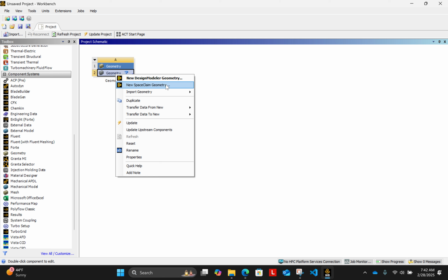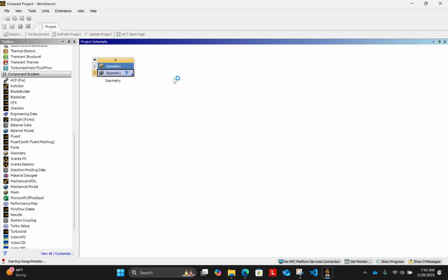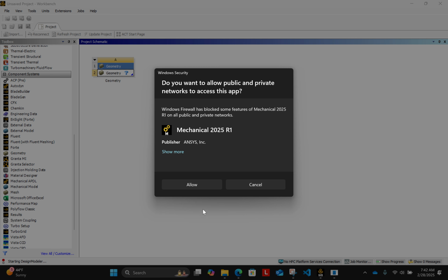They introduced another CAD software that is not included in their 2025 version, so you might actually see three software here. The software we want to use is Design Modeler. Design Modeler is the oldest CAD software that was incorporated in ANSYS, and it does the job fine. Okay, so right click and then open the Design Modeler.